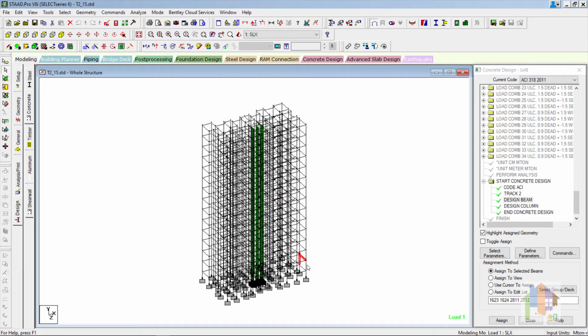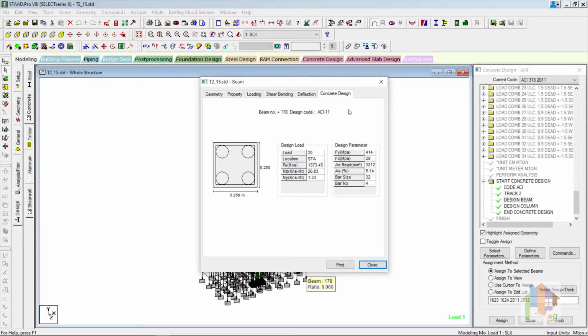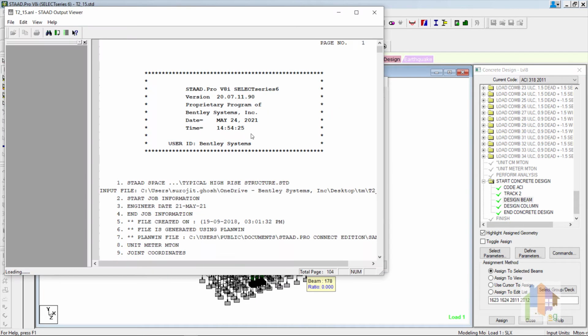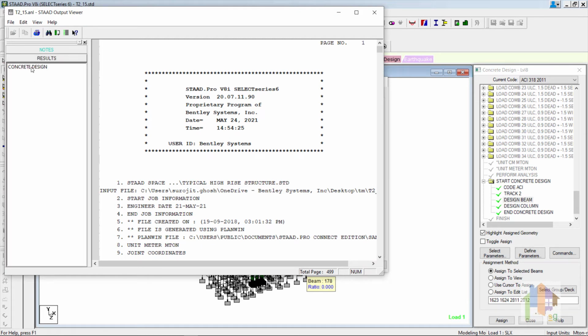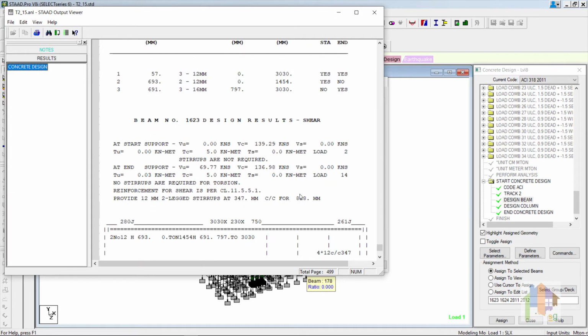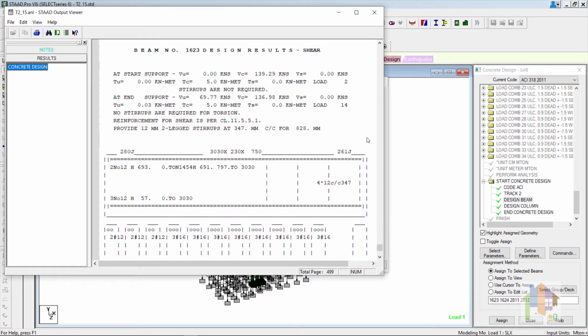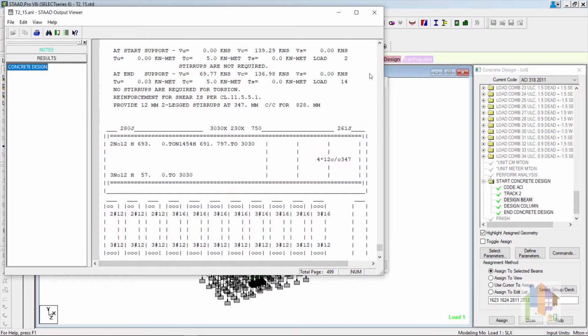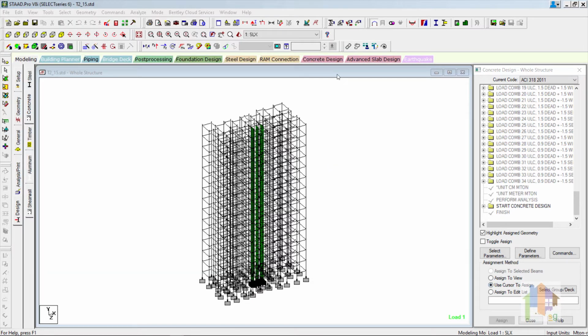For a column, just a cross-sectional view is provided. Neither tabular format output nor elevation and cross-section diagrams are provided. Generating the deliverable drawing files from these results is a tough and time-consuming job, as you need to first collect the reinforcement information for each segment, then rearrange it manually, and finally generate the drawing files. Only for simpler and small-scale structures like a pump house or small stockyard structure, this module can be used.